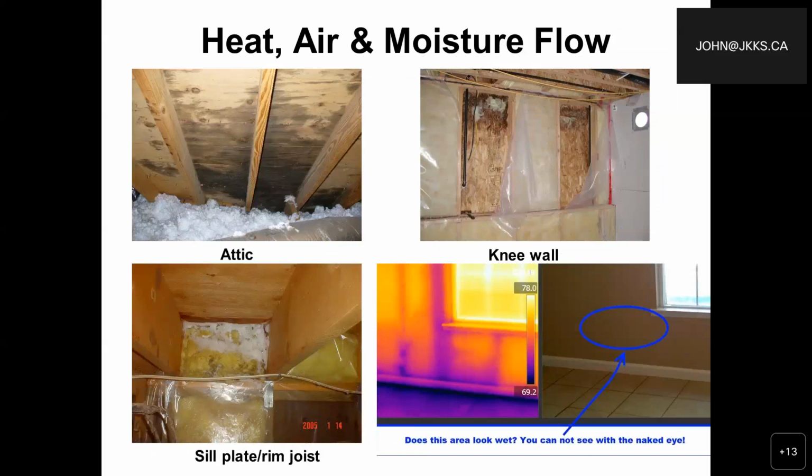We start with the upper left, where we can see an attic. In this attic, we have some nice fluffy, newer blow-in insulation. But what we also see is some darkening of the back of the plywood sheathing for the roof up in this attic space. Again, to me as an inspector, this is visible signs of moisture accumulation and condensation. And if we really take a look at it, the insulation is blown all the way over to the, we'll call it, lower edge of the roof, which means there's a lack of air movement for proper ventilation to reduce moisture buildup in an attic space.